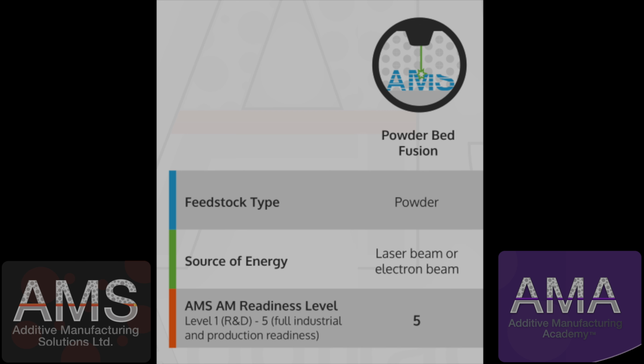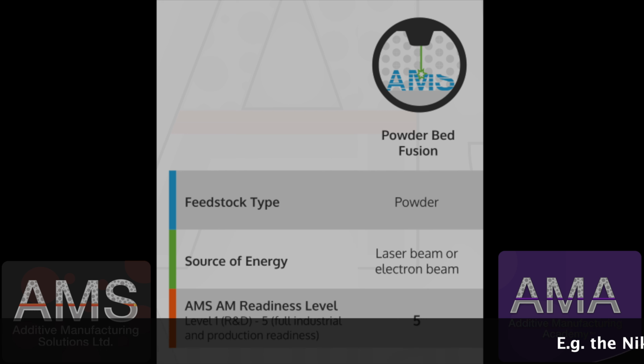In the case of metal powder bed fusion, we use a variety of different sizes of powder. We also have a variety of different alloys available that we can use. Ample development is currently underway to develop new materials, novel processes, novel methods in which we use these laser or electron beams. The development in laser powder bed fusion more recently has focused on larger machines with more lasers.